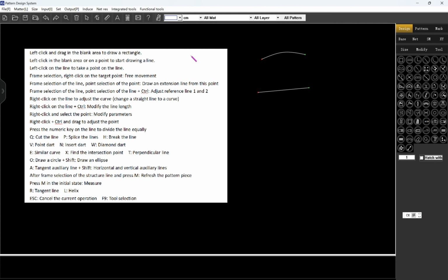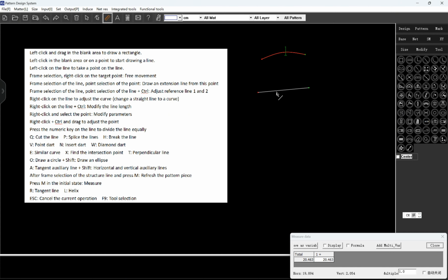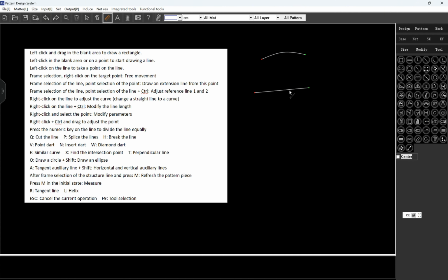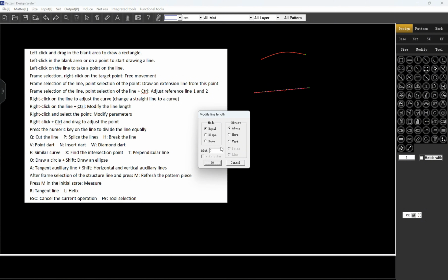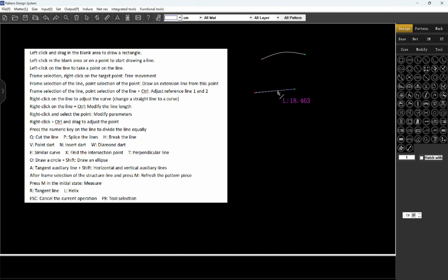The difference is 3. When I use the mirror tool and compare the two lines, we can change the icon here, minus, add. You can see the two lines, the difference is 3, because I set it back again. That was 25, now it's 20. Back to design mode, select this line and press Ctrl, click this line, and we make it different. The difference is 2, and we can change this to minus 2 and click OK. And we can see now this line is shorter by 2 centimeters than this line.